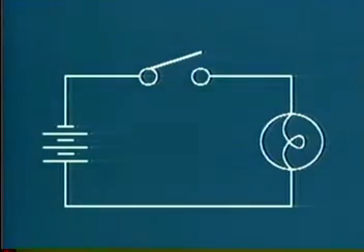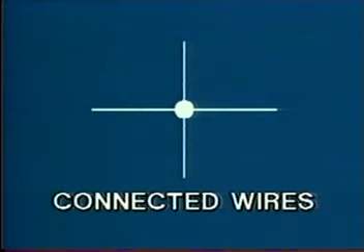In reading and drawing schematic diagrams, there are a few simple rules to learn. They are: 1. Schematic diagrams always use only electrical symbols. 2. Wiring leads from components in the circuit are represented by a straight line. 3. A heavy dot indicates a connection of 2 wires.